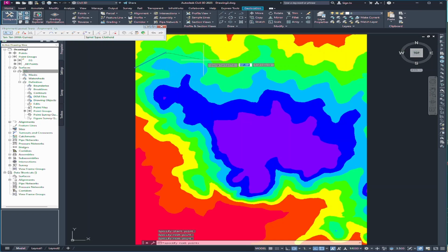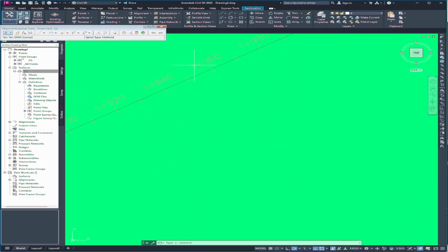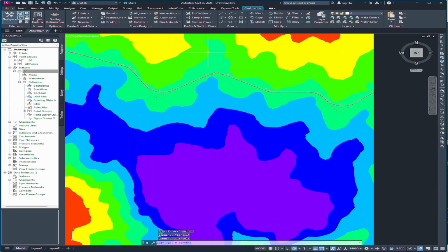I like to follow the similar elevation level, so there will be less cut and fill. If you go to a different elevation level, there will be quite large cut and fill. As I am creating the horizontal alignment, you can see I am creating several curves here, and at the end press enter and your horizontal alignment is created. You can see there is a label for each station, and there is a curve PC and PT, also the vertex in the middle. Close this one for now.